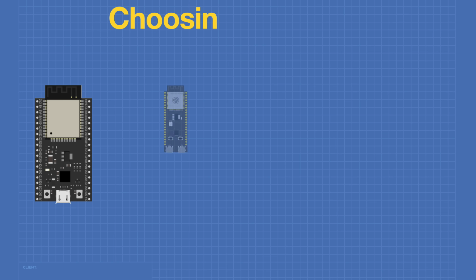So now that we've learned a bit about WLED, it's time to set it up. But before we do, we're going to need to select an ESP32. Now, not every ESP32 is the same, and some of them are better for specific applications than others are. So let's go and take a look at the criteria for selecting an ESP32 for use with WLED.